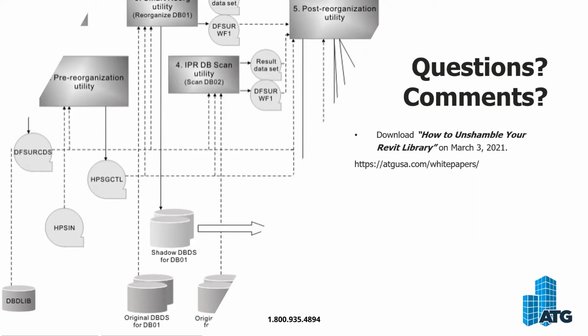Yeah, so Brian, there is a challenge in taking iterated families because man, if someone else did that, even if you do it, it's hard to keep it straight. When I do it, I tend to name them with an iteration number. Like if I started with outdoor lantern, then if I make changes to it, I might call it outdoor lantern 2. If I didn't do it with the naming, I can also check the Windows properties and see when it was last modified. So that's not going to be when it was last looked at or opened.